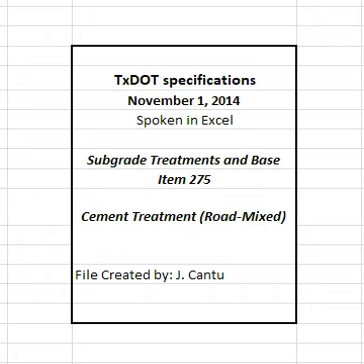5.2 Cement treatment. Cement treatment will be measured by the square yard of surface area. The dimensions for determining the surface areas are established by the widths shown on the plans and lengths measured at placement. 6. Payment. The work performed and materials furnished in accordance with this Item and measured as provided under Measurement will be paid in accordance with Section 275.5.1, Cement, and Section 275.5.2, Cement treatment.